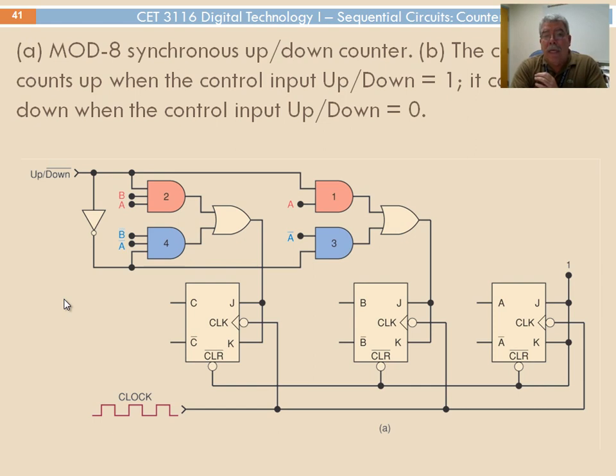We're still using the JK flip-flops, and we have an array. If you remember how we used the AND gates in the synchronous counter of 3 bits. Remember, if you look into the truth table, whenever you want to force the change in the most significant of the bits, having A and B both at 1 will provide a transition to 1, 0, 0, right?